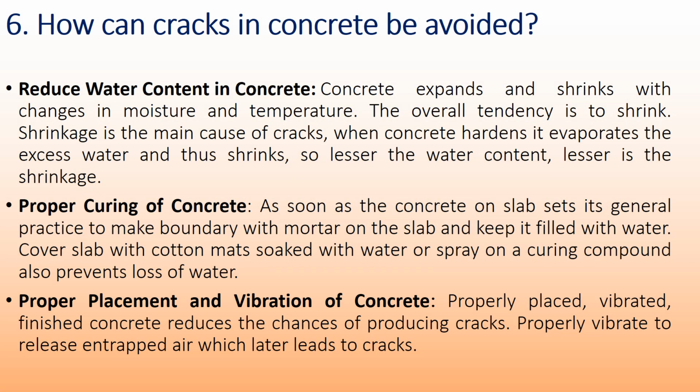The next question we discuss is: how can cracks in concrete be avoided? Cracks in concrete can be avoided by using solutions such as: reduce water content in concrete. Concrete expands and shrinks with changes in moisture and temperature. The overall tendency is to shrink. Shrinkage is the main cause of cracks. When concrete hardens, it evaporates the excess water and thus shrinks, so the lesser the water content, the lesser the shrinkage.